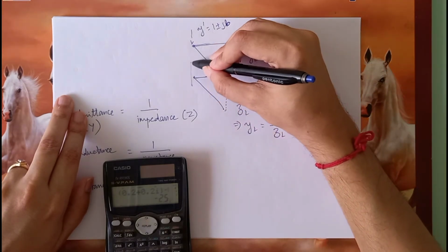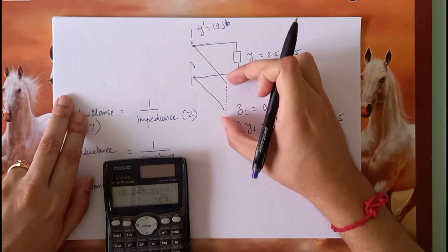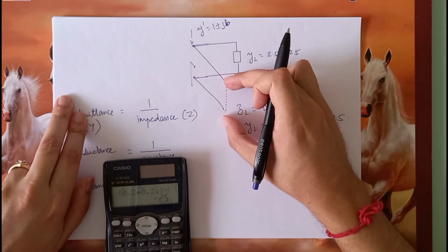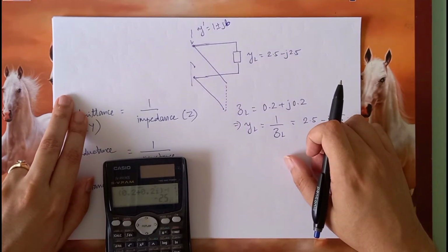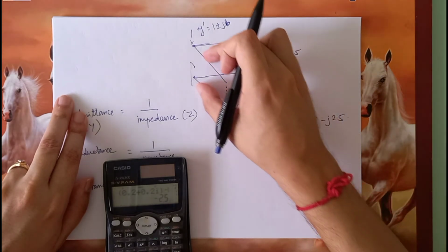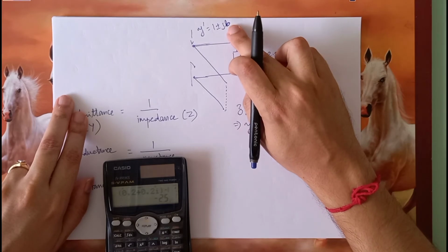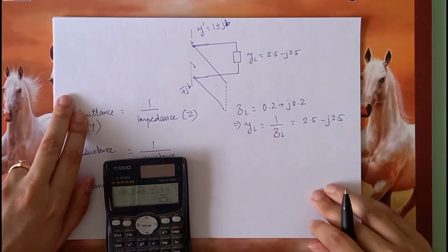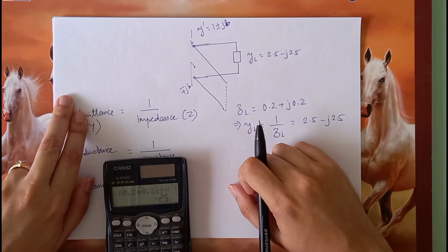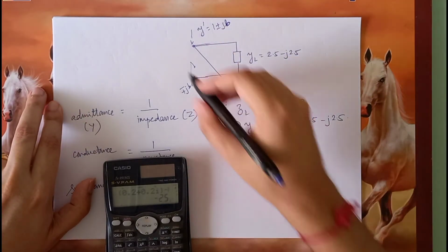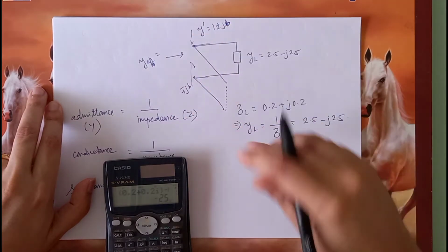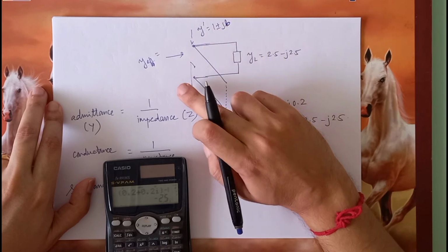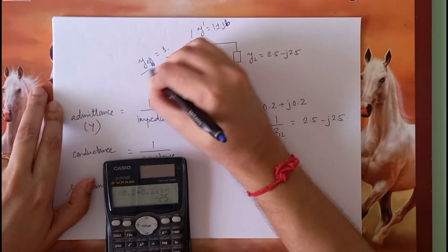such that the reactance offered by this. Now, as you know, a transmission line that is terminated using either open circuit or short circuit can never have any real impedance. Even if you move further away from it, it can only have imaginary impedance or admittance. So therefore, the susceptance of this line should be exactly the opposite of this susceptance, that is minus plus jb. So because these two are in parallel, the admittances will get added up. Therefore, the effective normalized admittance will be 1 plus minus jb minus plus jb, which is equal to 1, which makes it matched.